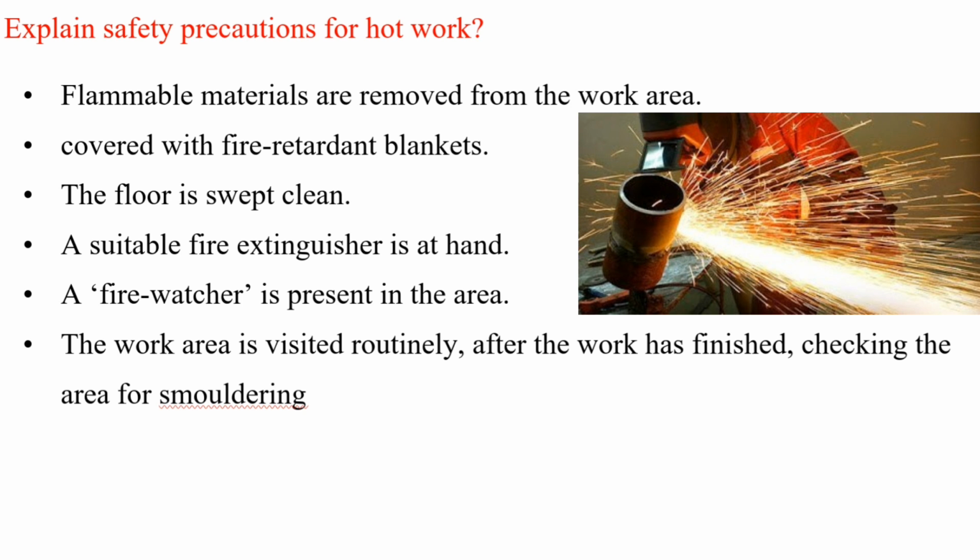Explain safety precautions for hot work. Flammable materials are removed from the work area, or covered with fire retardant blankets. The floor is swept clean. A suitable fire extinguisher is at hand. A fire watcher is present in the area. The work area is visited routinely, after the work has finished, checking the area for smoldering.